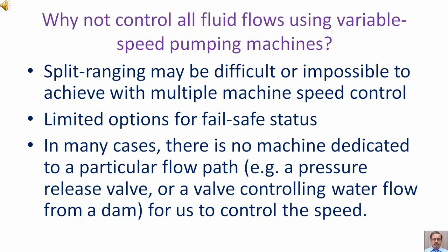Split ranging may be difficult or impossible to achieve with multiple machine speed control. Limited options for fail-safe status. In many cases, there is no machine dedicated to a particular flow path, for example, a pressure release valve or a valve controlling water flow from a dam.